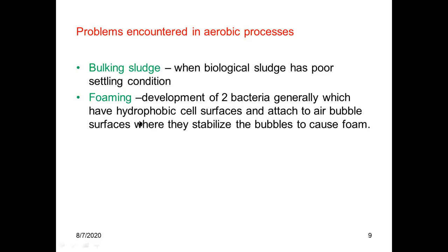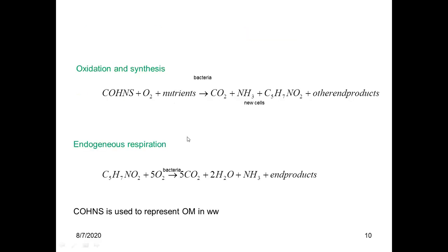And foaming means foam is formed. It is caused by the development of bacteria which generally have hydrophobic cell surfaces and attach to air bubble surfaces, where they stabilize the bubbles to cause foam. So foaming is another problem. Because of that, the air will not come from the atmosphere into the water. So it is a problem. Then here is the reaction for aerobic oxidation of organic matter in wastewater. In the previous lesson you learned that one equation.